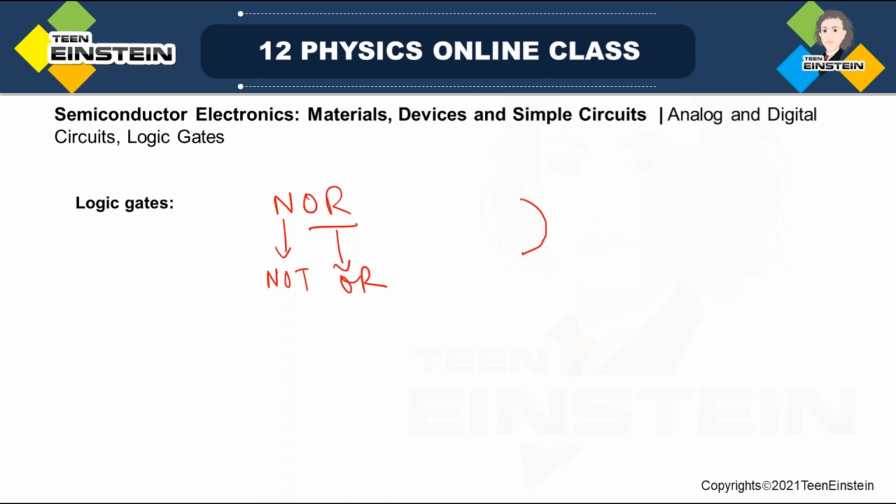So OR gate I'll draw first. OR gate, along with that there will be a bubble over here. If you have a bubble, then it is representing that there is a NOT operation just after the output of OR gate. So in this case also you can have more than 2 inputs. Let me take only 2 for the understanding purpose. So this is the NOT operation. Here it is the ultimate output.